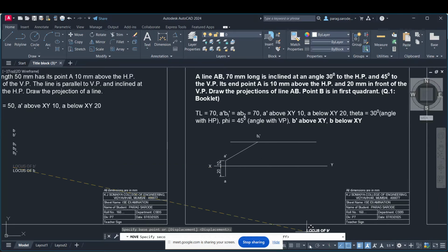Again, I need to switch off this ortho, right? In this way. You can see now, while moving, a point triangle is coming here, right? See, if you're facing troubles here, what you can do is switch off the O snap and then you place it in this way, right? So that will help to properly place all the annotations.